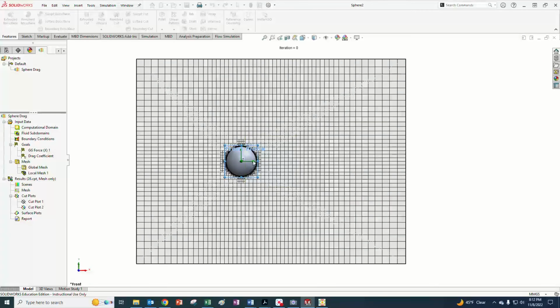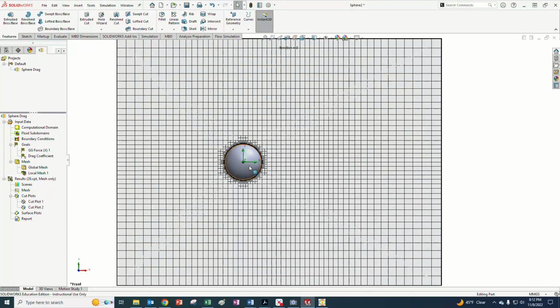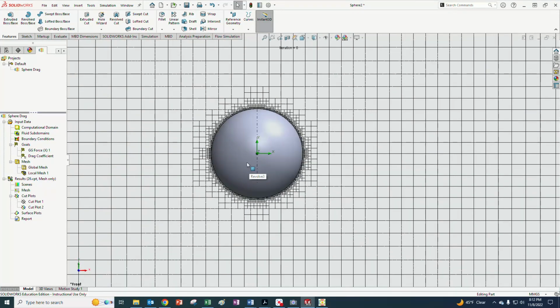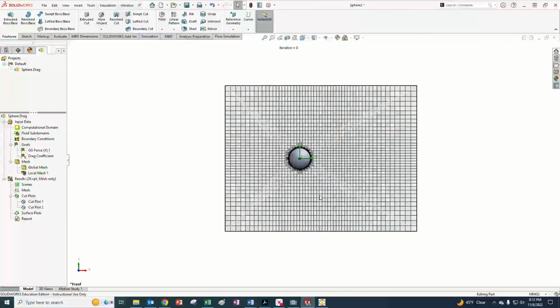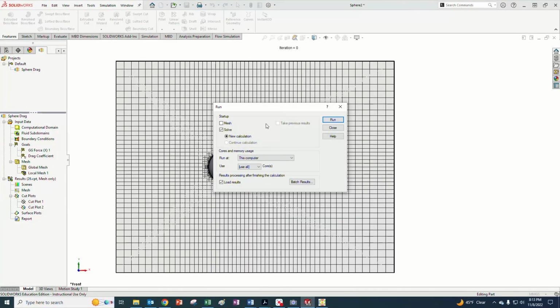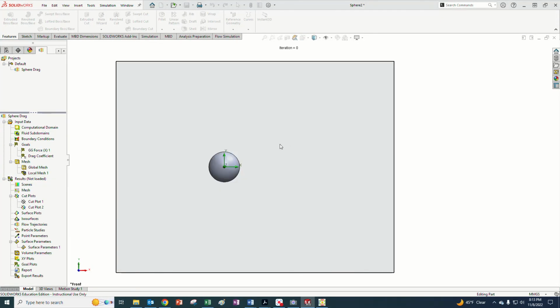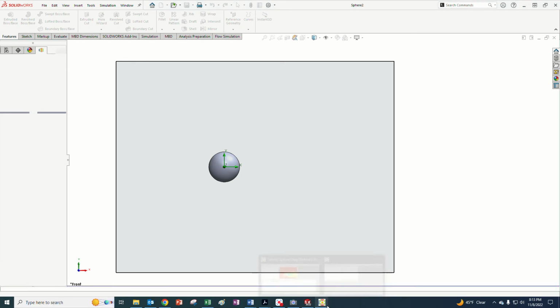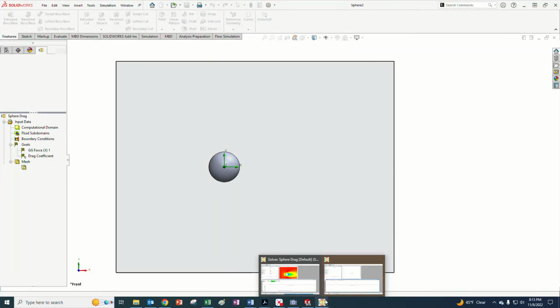And so now you could see what the mesh refinement looked like, and it looks like it makes it better. We could run it and we can see what the effects are pretty easily. Run. We've got to be careful not to go too fine of a mesh, but let it solve. And we want a new calculation. We want to be careful, when you do this, not to just run it over the old calculation if that's an option. But it should pop up a new one of these windows.